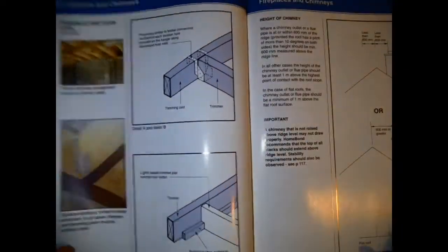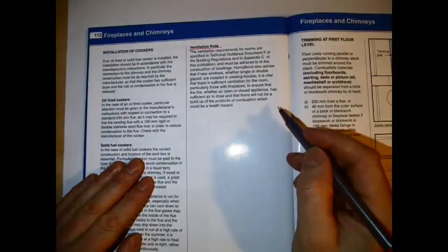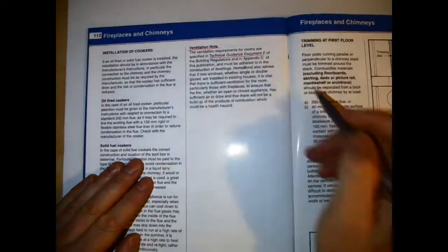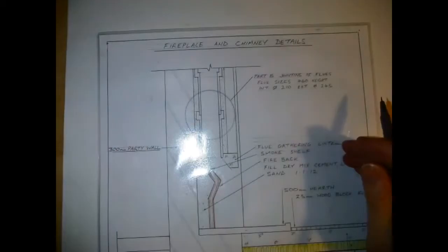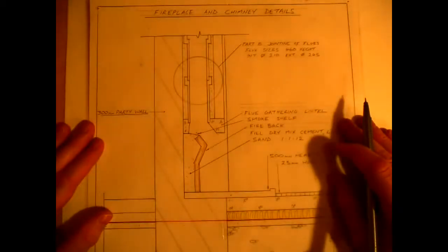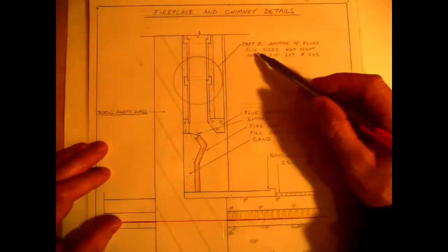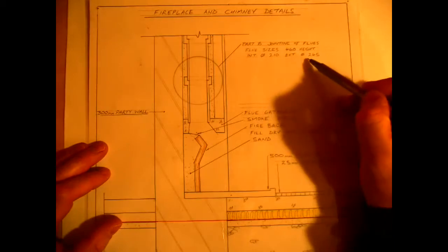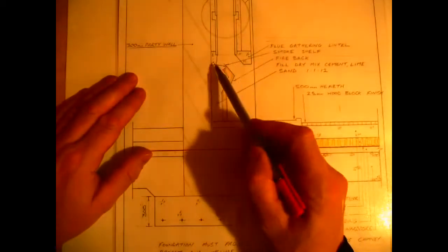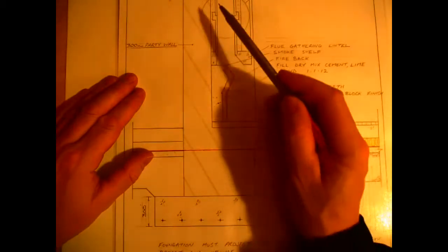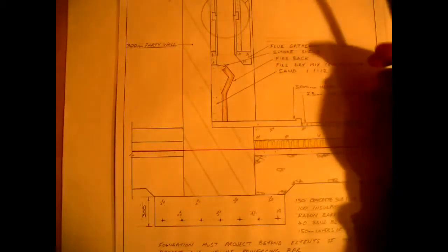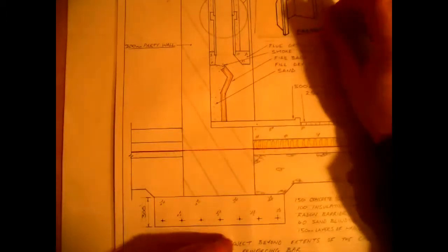Now, other than that there, other details that are worth a look are regarding ventilation requirements. If you don't have adequate ventilation in the room, you will not have sufficient draw to have the fireplace working efficiently, and the gas is combusting, and that's a serious problem, so that has to be accommodated. This is a question that came up in 2002. It asked about how the flues are jointed, and they're a pumice fire clay, and they have a spigot on them which they insert into each other. Usually a rebate can be in those as well.